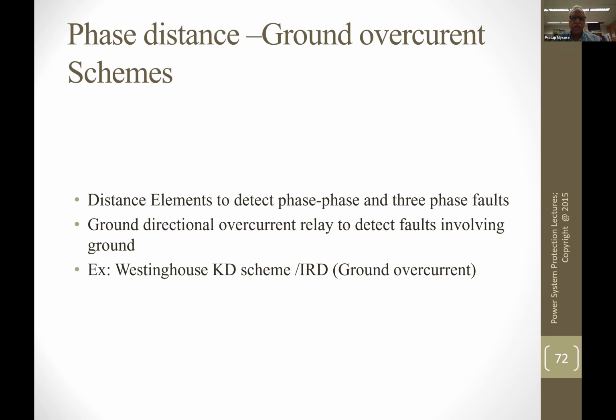So if, in the electromechanical world, we had to put these, which are all single-phase measuring elements, I should have put 6 boxes for this, for zone 1. And then you need 6 more boxes for zone 2 to provide protection for the last 15% of the line section, because zone 1 is set to 80 to 85%. So instead of that, they came up with a very brilliant technology.